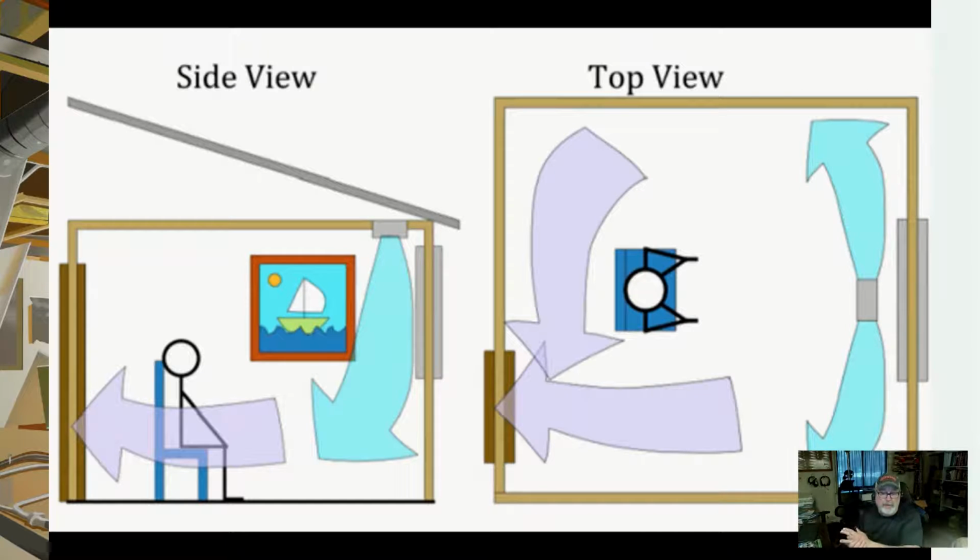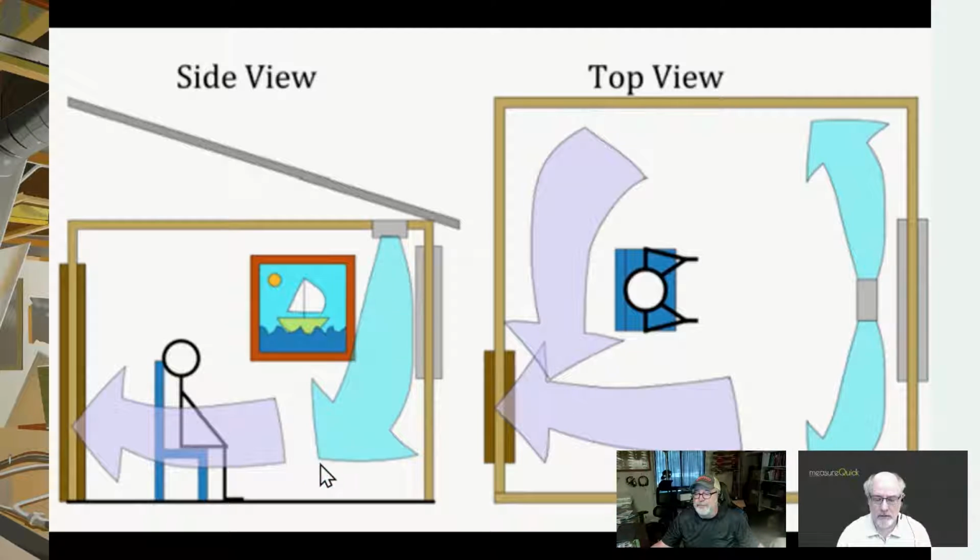But when you have properly sized equipment, you get these nice long run cycles, and the air will have time to mix with the entire house, and it passes through the system several times. And then where you put the register has much less import than if you oversize the equipment and have short cycles. So it's kind of an interesting study.